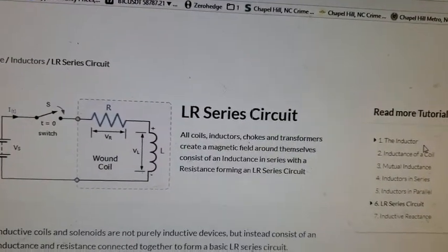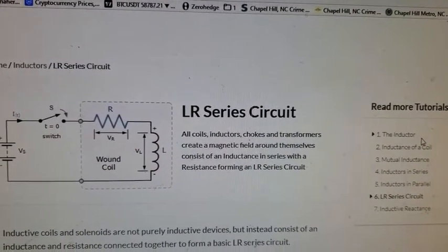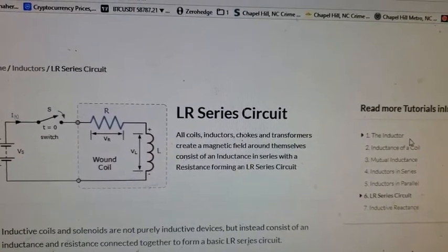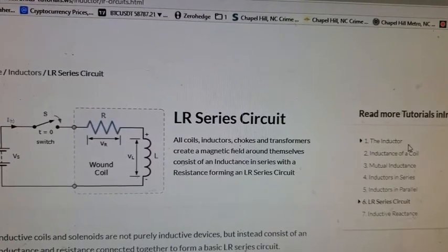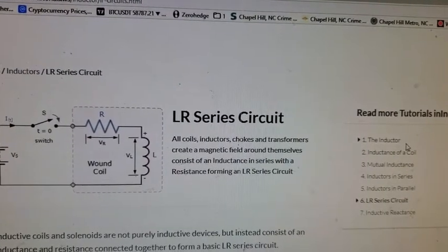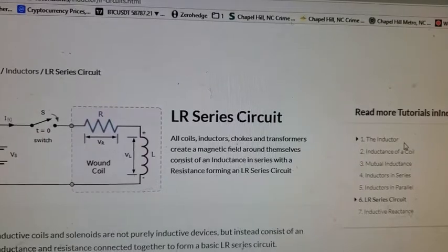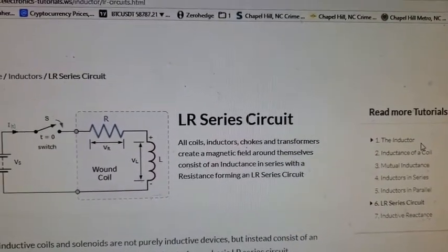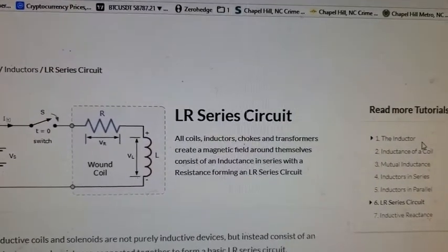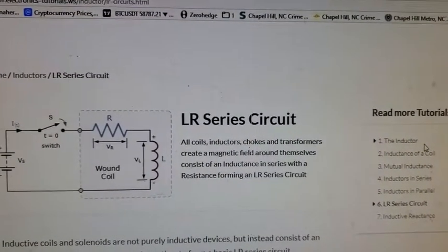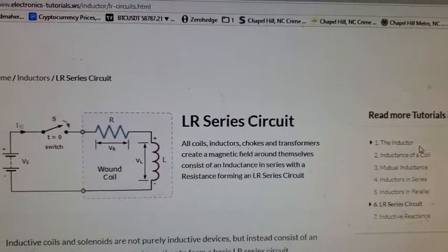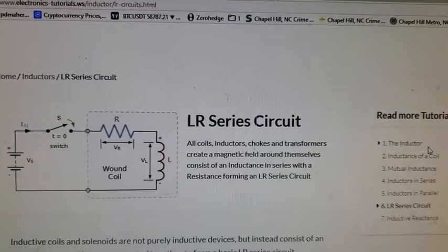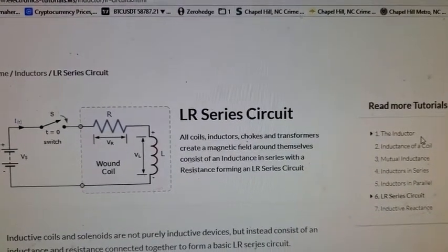This induced dynamic resistance will be greatest when the rate of magnetic flux change per unit time is greatest, and will no longer be present when the inductor is fully saturated and at its maximal field strength for the given voltage applied to it, as at that point there is no longer any further change in the magnetic field and hence no further induced magnetic field.